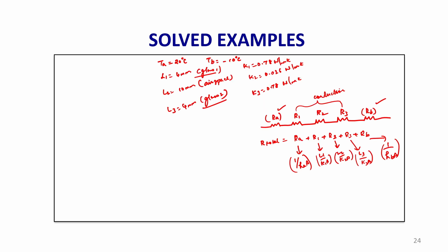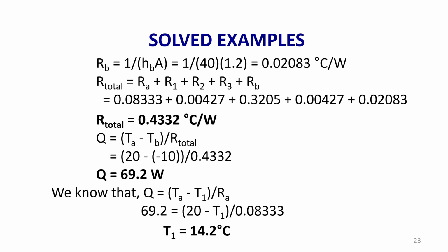Okay. So, we have solved this problem and we got a reduction in the heat flow from the previous one, which was 266 watts, if you remember, the one which we took as the previous problem. So, there is a reduction in the Q due to the change in the resistance, the total resistance of the composite wall. Because of this, the temperature also changed from minus 2.2 degrees centigrade to 14. This is a desirable temperature because when we have a negative temperature, there are chances of fog formation, especially when the humidity of the air inside the room increases.